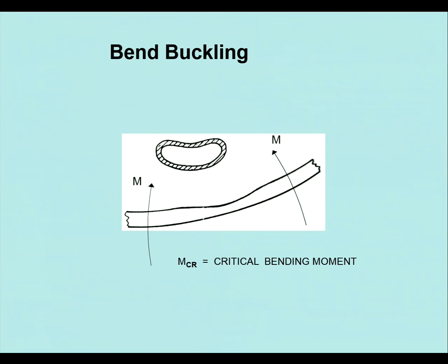we don't normally put concrete on. When we put concrete on to weight pipes down, we don't consider its strength at all, so we just ignore it. But for those big pipelines, there's a very big one that I was involved in down in Brazil, and I could walk inside it. It was bigger than me, and it had concrete on it about that thick, and so that made a big difference to the structure.